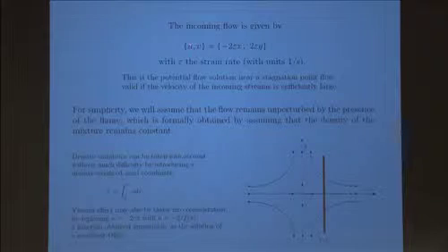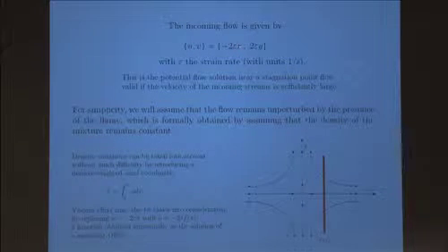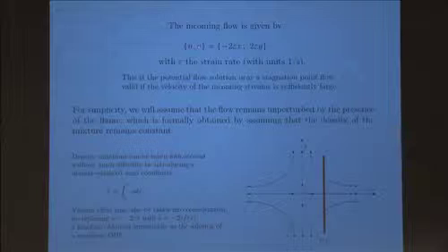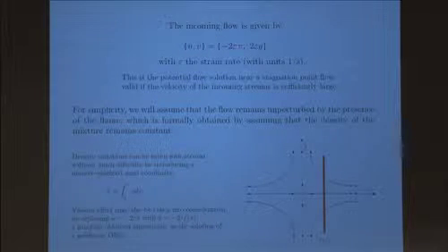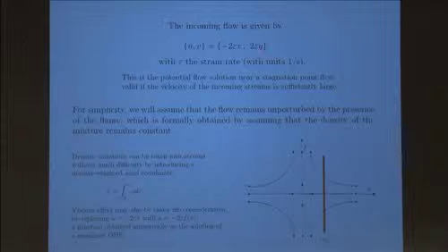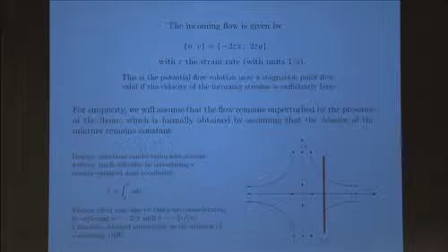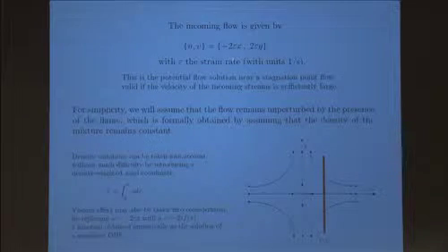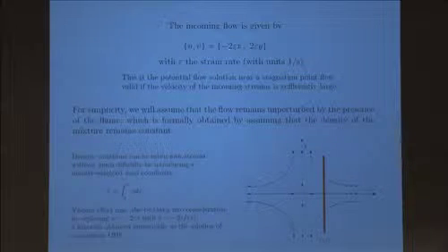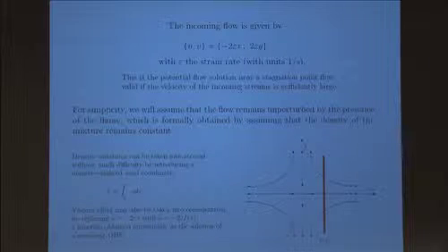The potential flow is that the axial velocity is minus 2 epsilon r, and the transverse velocity is 2 epsilon x, and this is 2 epsilon y. The 2 is just there for simplicity because the solution will take a simpler form when you put a 2, but all it means is that 2 epsilon is the strain rate, okay, not epsilon. But okay, so this is a flow that has a constant strain at epsilon. Epsilon has units of 1/s. We discussed this before for premixed flame.